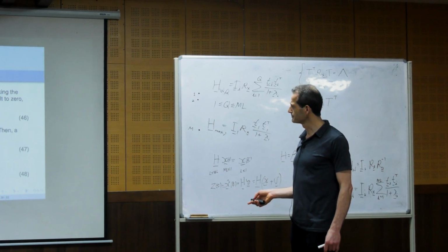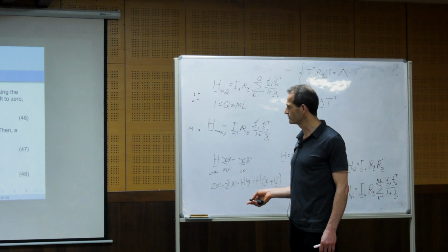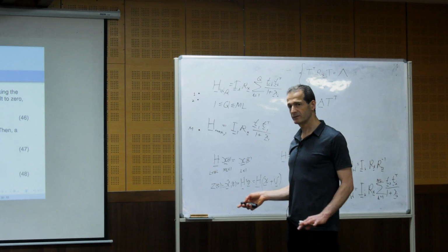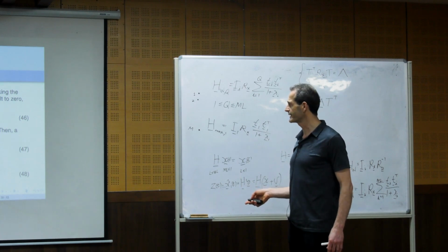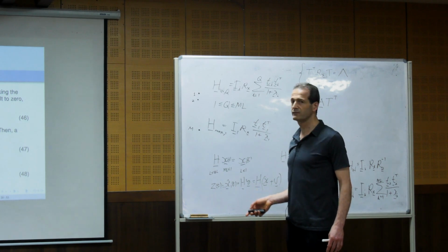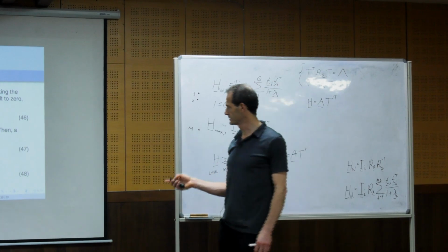Sometimes, even the small eigenvalues, you see, the small eigenvalues, sometimes we put them to 0 because this becomes a large value, but this will create some distortion. So here we take all the non-negative eigenvalues, we invert them, and this is a pseudo-inverse of a diagonal matrix, which is very easy to do. See? So this is the matrix of the MVDR.